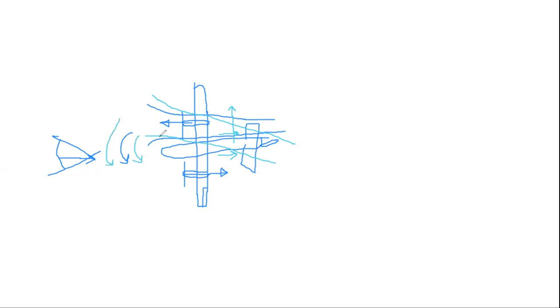So you have one turning force from thrust asymmetry, but you have an increment of this turning force when the slipstream affects the rear part of the fuselage. And it is also very important to test the aircraft in a wind tunnel in asymmetric flow in the engine out case.